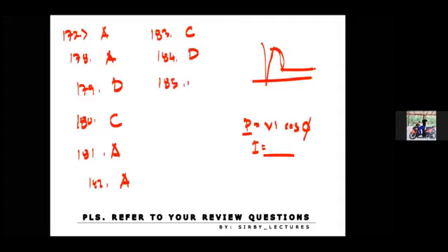Number 185. A motor mounted in an axial fan for the blower of a flatbed dryer is operating at higher than normal temperature. So most likely, what are the possible causes? For letter A, it says that it is overloaded, and for letter B, it says that there is a loose connection in the overload relay, and for letter C, the line frequency is incorrect, and letter D, it is a hot summertime.